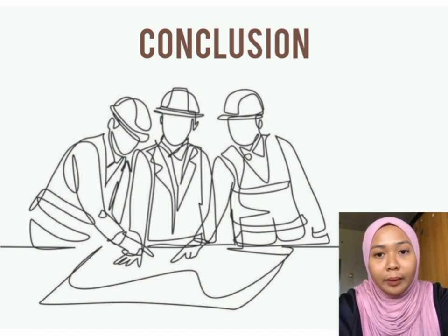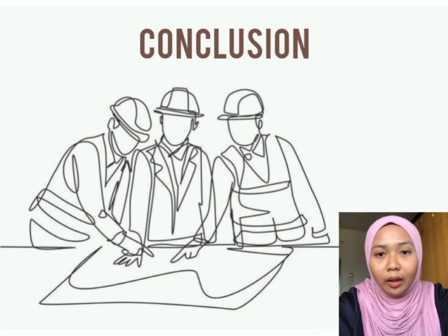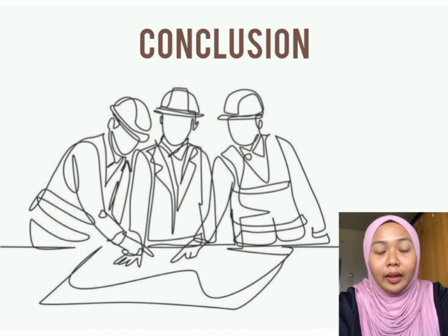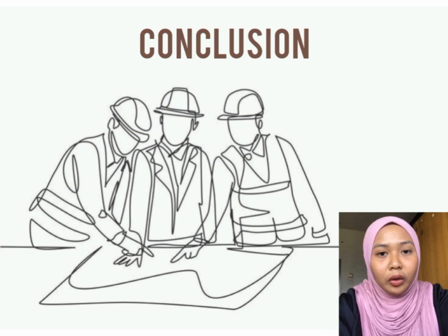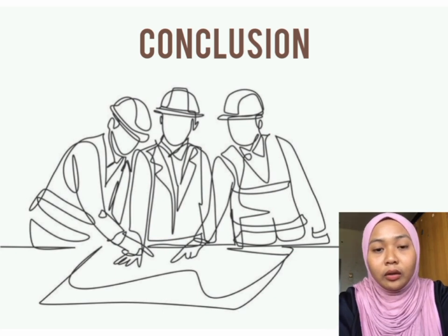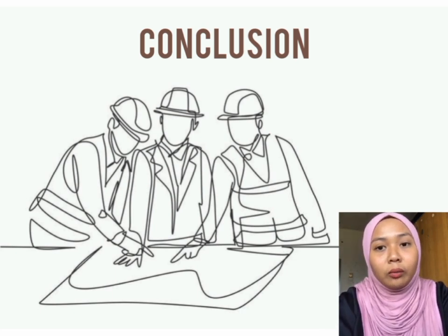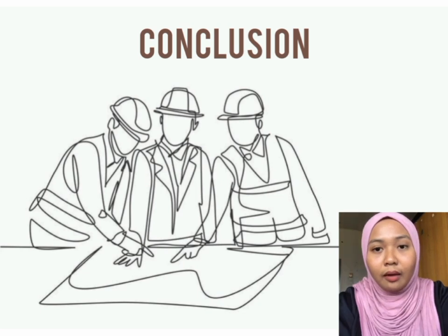There are several types of demolition works. So it shows how we carry out demolition work. In this case study, the type of demolition method that has been used is progressive demolition, where the demolition process is done part by part and from the top of the structure to the ground. Demolition work in the construction sector means demolishing buildings and other structures that bear loads or otherwise relate to the physical integrity of the structure.